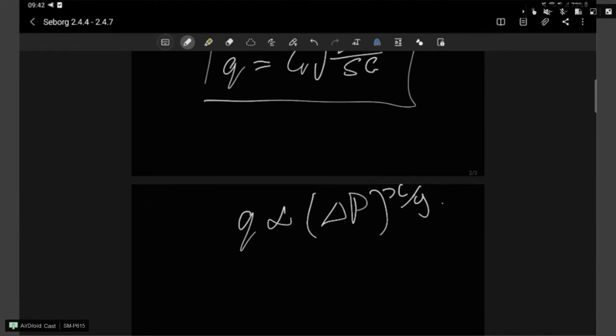An elbow can be seen as a similar thing, because the change in flow caused by that elbow is dependent on the roughness and all those sort of things inside the physical piece of equipment. So it's basically an adaptation, as you mentioned: if there was just a pipe, we get X flow rate, but now that we have this restriction, we need to adapt for that pressure loss or for that flow.